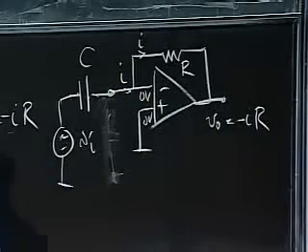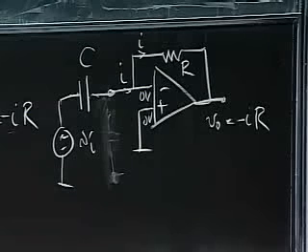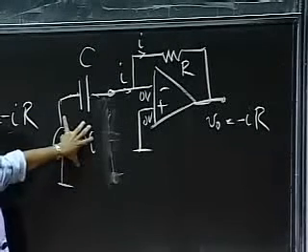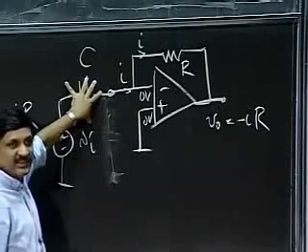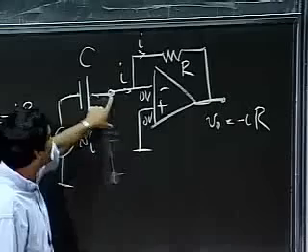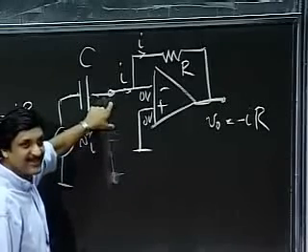Just remember these 4 or 5 little tricks, and you apply them in op-amp circuits again and again and again. So this is VI. This is my virtual ground. So as far as this poor little capacitor is concerned, it's chugging along merrily, thinking that it's connected to ground. Little does it know it's only a virtual ground.